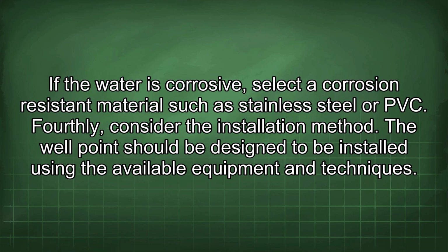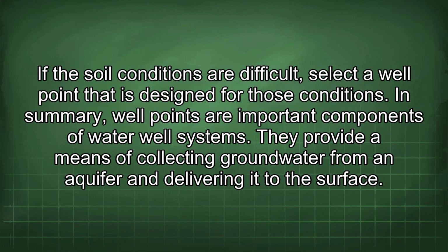Fourthly, consider the installation method. The well point should be designed to be installed using the available equipment and techniques. If the soil conditions are difficult, select a well point that is designed for those conditions.